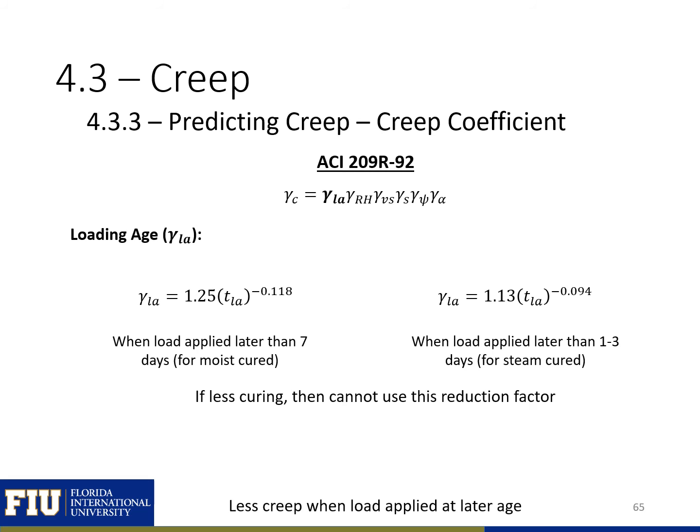So the first factor that we're looking at is our loading age factor. We have two different factors that we can use if we're using moist cured or steam cured concrete. And here we're plugging in the time when we're loading our concrete.